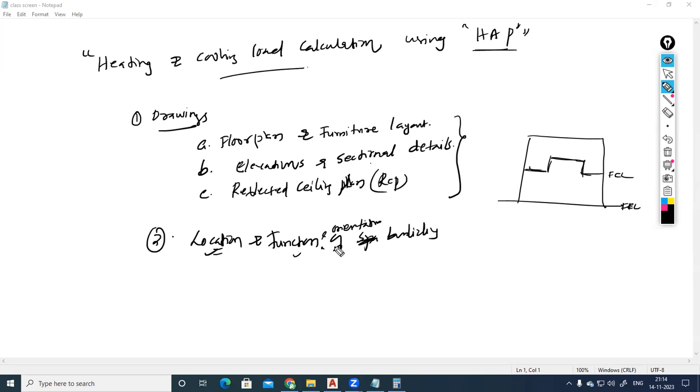Because the heat ejected by people is not uniform. For example, if you are designing a gymnasium, the level of activity the people will be performing will be different compared to a library. Also, the electrical equipment demand, or the load demand, within the gymnasium is higher than the library or classroom. That's why the function of space is mandatory to know to perform our design.